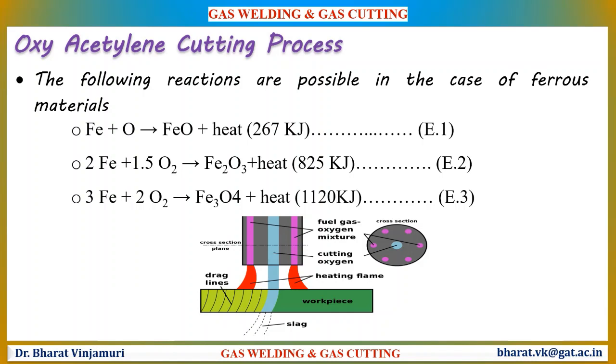There are certain disadvantages in using gas cutting process. This process is limited only for cutting carbon steels. As compared to mechanical cutting, dimensional tolerance of this process is a little poor. The workplace needs to have adequate ventilation, and the quality of the process purely depends on the cutting speed.